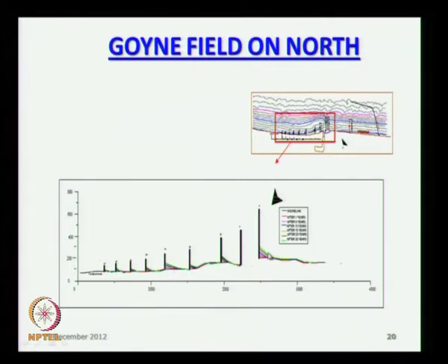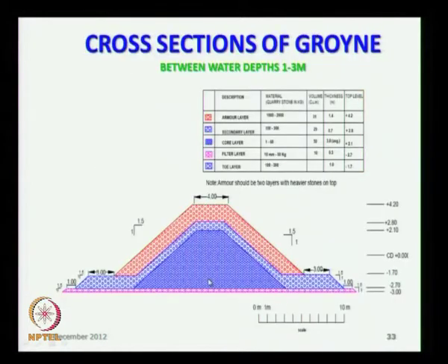Generally the shoreline is advancing on the southern side, and the seawall is built beyond this last groin, right. We have the groins and we have the seawall. For this artificial nourishment as a stockpile, we will fill up to this point originally itself. Whatever we have filled may get removed over a period of time. At Ennore port we have done the stockpiling, and I will show the photograph of how we have done that.